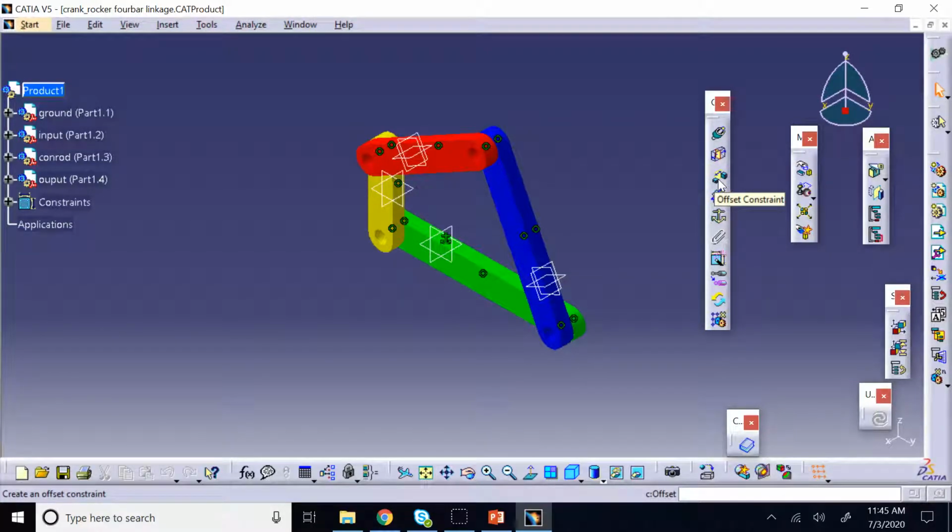So we put two faces at a fixed distance from each other, flat faces. And then we can provide a contact between the members. So when we say contact, they can slide in one direction, but in the other direction, normal to the faces, they cannot move. Okay, you can fix two members together at the current configuration, and so on and so forth. And then we can convert a rigid assembly, subassembly to flexible, and so on.